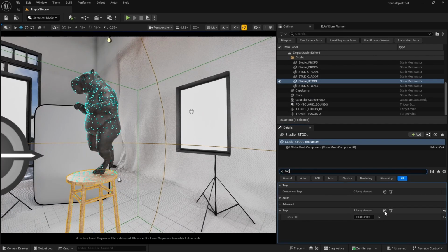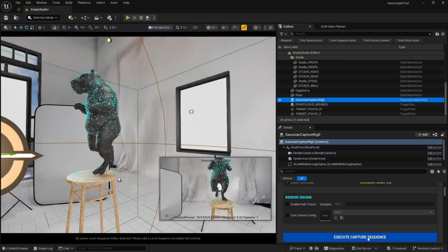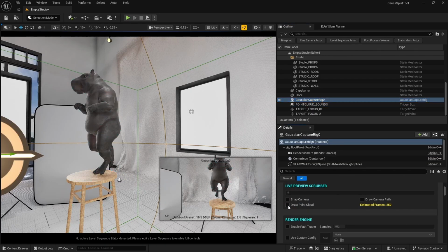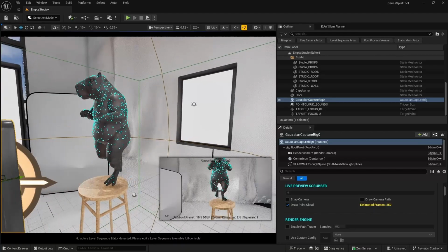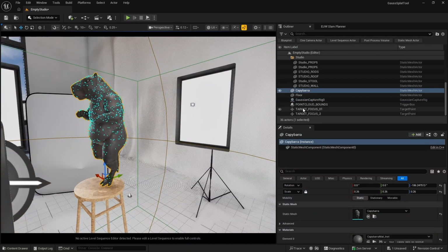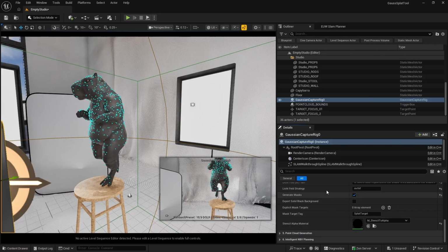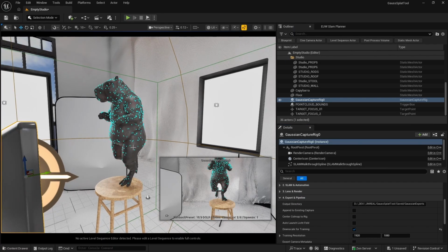If I look here and I delete the tag and then I do some updates here on the generate flight path, you see it's gone. The point cloud is only available for the guys with the tag if the masking option is on. That is, if you have the generate masks on, it will only generate point clouds for the tagged objects.